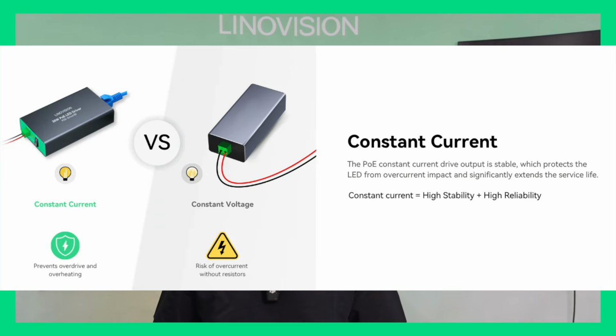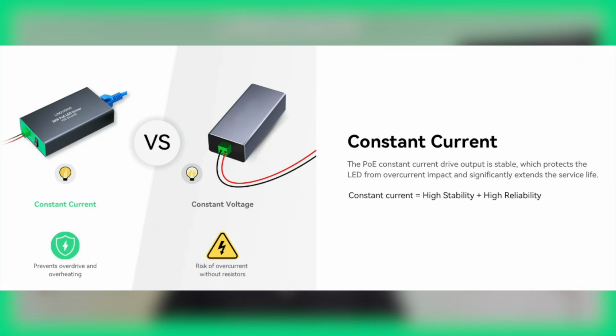That compliance range matters. 3 to 36 volts covers a wide range of LED string configurations, series strings, shorter parallel arrangements, which gives you design flexibility at the fixture level without having to build around a single fixed output voltage. The constant current architecture is a critical part from a lighting quality standpoint.